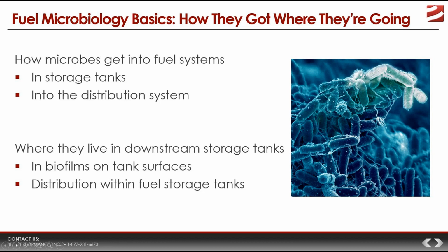There's tons of microbial presence on that. And not to mention if you get water ingress, like a couple gallons of water from a spill bucket when an underground tank gets opened, the water rushes in, and that water's teeming with microbes.